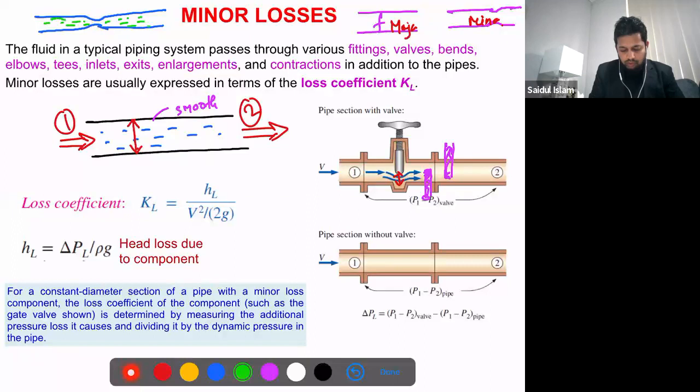so if the flow is fully developed here, you will see it will become like this again when it is a long pipe. So there will be some gradual transition of the flow. If you have just one narrow section, this kind of contraction in the pipe. But if you have multiple like this in a short distance, then the flow will not get enough space. And in that case, there will be more loss.